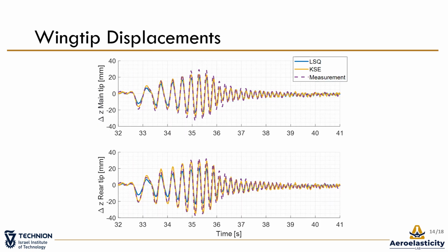On these slides are displacement reconstructions at the wingtip, an extremely remote location from the Kalman state estimator input sensing points. The Kalman state estimator error is mostly within the motion recovery system error range. The maximal Kalman state estimator error is about 4 mm. Overall, the finite element model strain mode sets deliver quite good shape estimations. What about the ground vibration testing set?